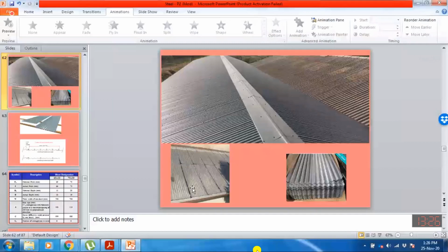And we need to consider that the load is acting in the downward gravity direction. So the span will be equal to the horizontal distance between this panel point and this panel point, which is equal to the panel length. And we are assuming that this beam has unit width. On this sheet, we have the load acting per unit area. The total load is acting on this area, meaning on this width and on this length. If I multiply the load acting per unit area by this width, I am converting this load into a UDL, which is uniformly distributed along this length.